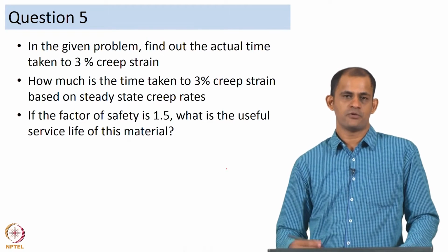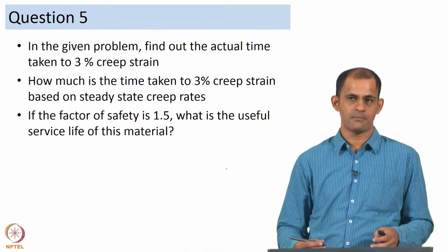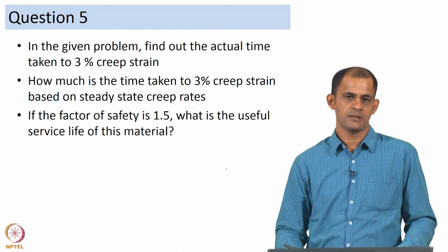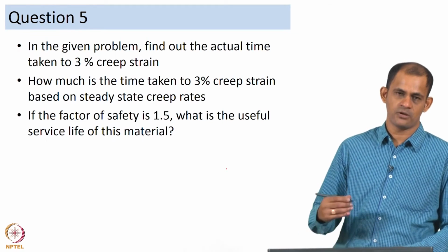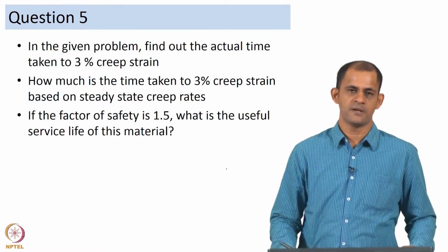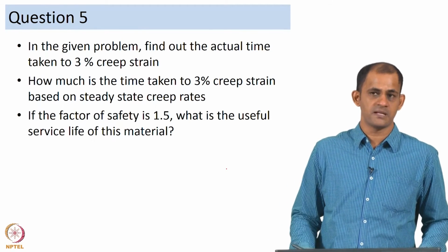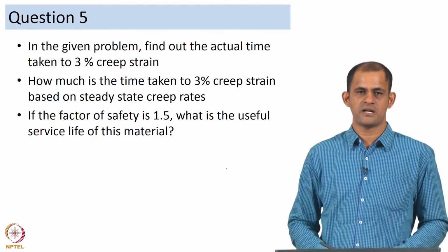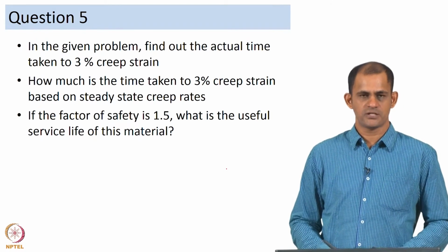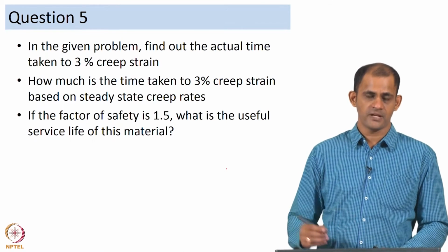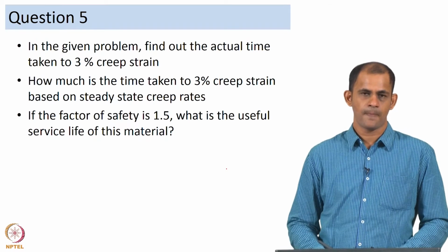And if your program is accelerated, in the sense you are trying to develop a product quickly and you want to know the behavior of the material in quick time, you cannot afford for the material to go till failure, because in that process you are going to spend months of time just to get a basic understanding of the creep behavior of the material. So, typically what engineers tend to do is they allow the material to enter into the steady state creep range.